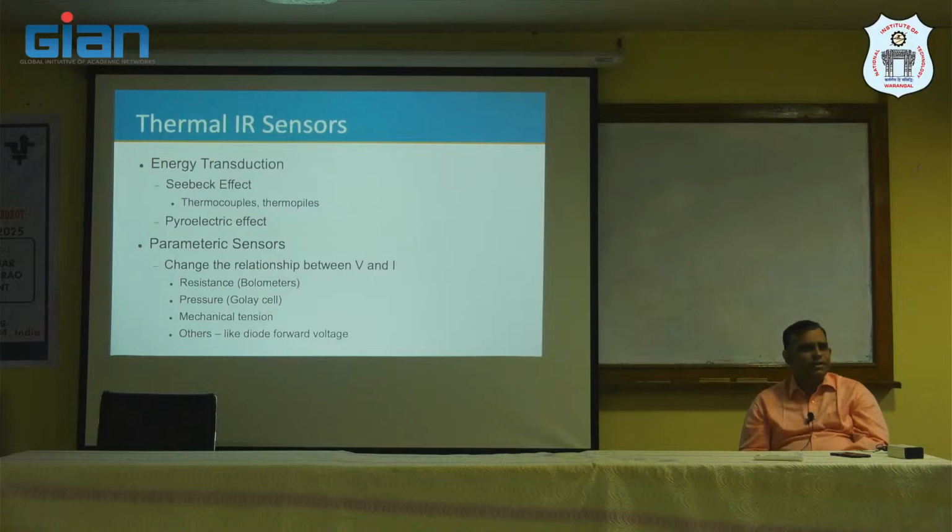Remember, you have done quite a lot of diode equations and transistor equations. Temperature always appears one way or other. If nothing else, kT, where k is the Boltzmann constant and T is the temperature, appears at many locations. So wherever it appears, whatever my output of semiconductor material is going to be, it's going to be temperature dependent. So I can use that as a temperature sensor. If nothing else, you take a diode, just design a simple diode, measure its current, that is a temperature sensor, if we can dissolve it into very small amounts.